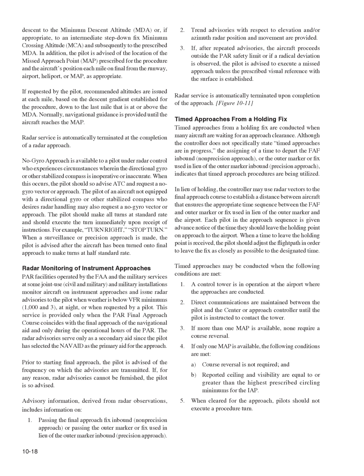Figure 10-11, timed approaches from a holding fix. Timed approaches from a holding fix are conducted when many aircraft are waiting for an approach clearance. Although the controller does not specifically state timed approaches are in progress, the assigning of a time to depart the FAF inbound, non-precision approach, or the outer marker or fix used in lieu of the outer marker inbound, precision approach, indicates that timed approach procedures are being utilized.